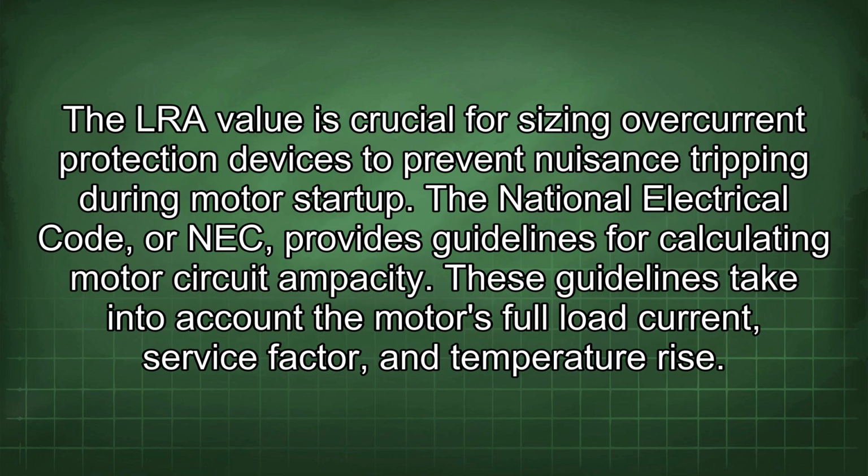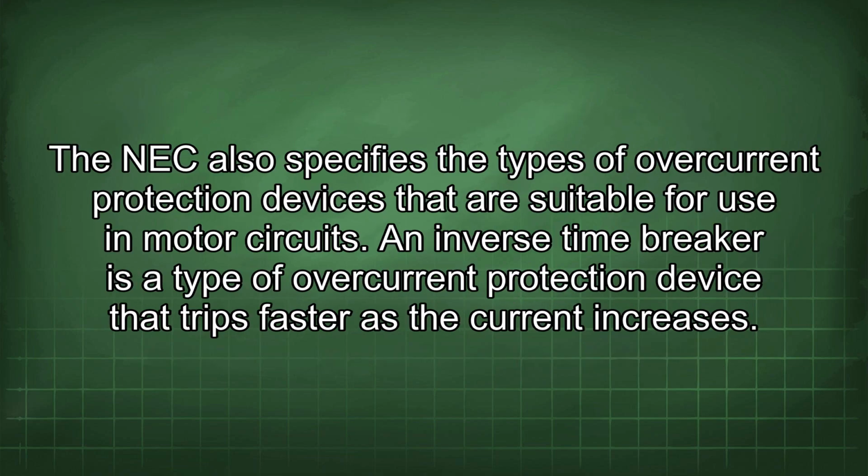The LRA value is crucial for sizing overcurrent protection devices to prevent nuisance tripping during motor startup. The National Electrical Code, or NEC, provides guidelines for calculating motor circuit ampacity. These guidelines take into account the motor's full load current, service factor, and temperature rise. The NEC also specifies the types of overcurrent protection devices that are suitable for use in motor circuits.